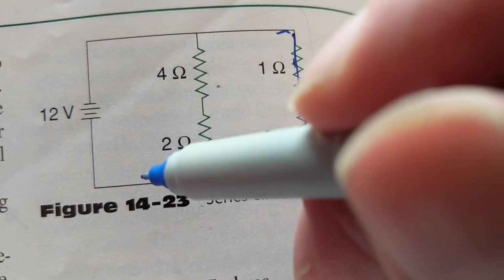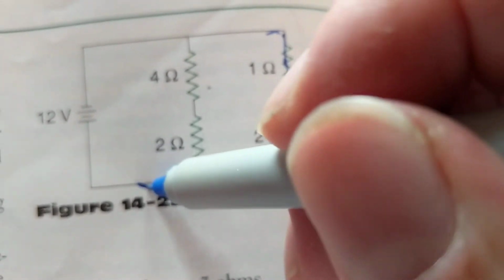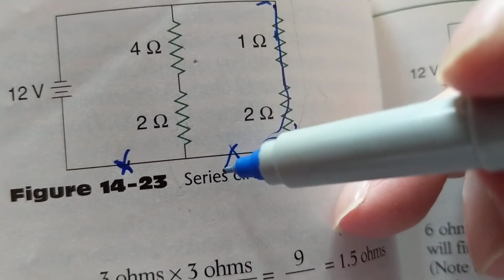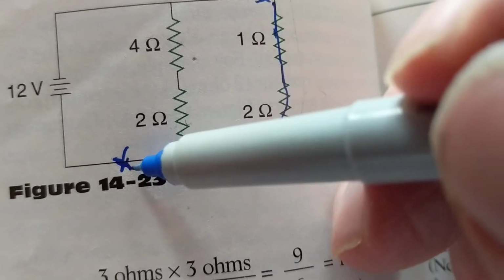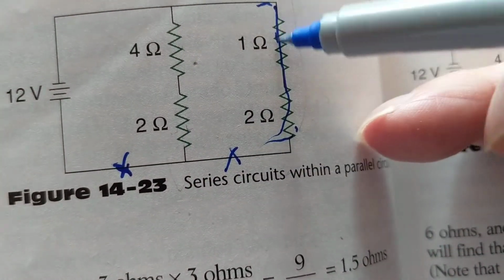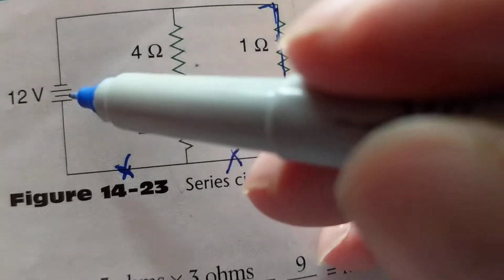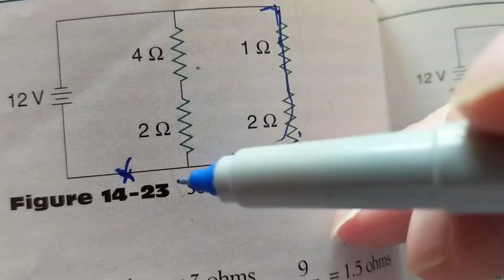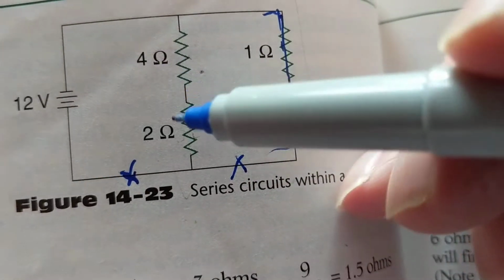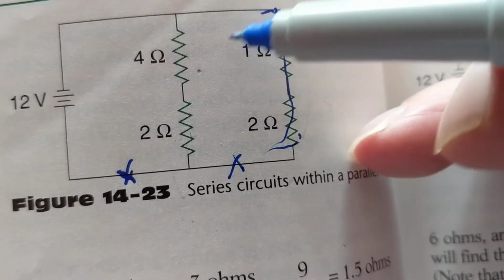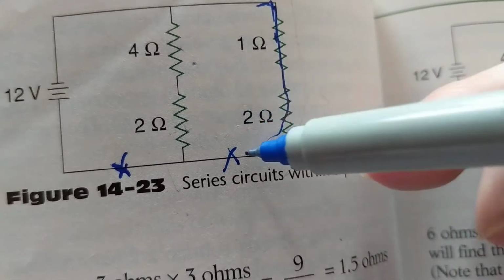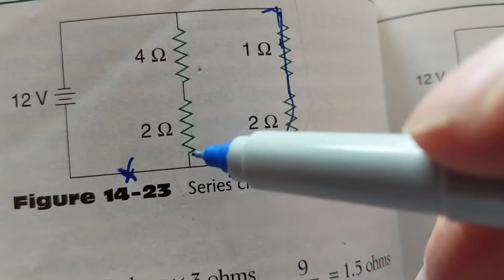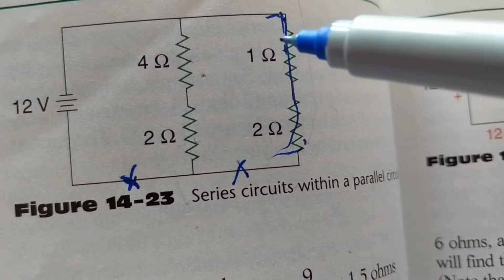Let's say the open is here. Uh-oh. This is why I had to use a pen today. Open is here. Now what happens? Now we're in trouble. Current cannot flow to either path. Current comes here, tries to come here, and says, you know what? I have no path to get back to where I wanted to go, to the battery. It knocked out both. So you see, wherever the open is, if the open is here, here, here, here, it makes a difference. Because this wire is common to both.